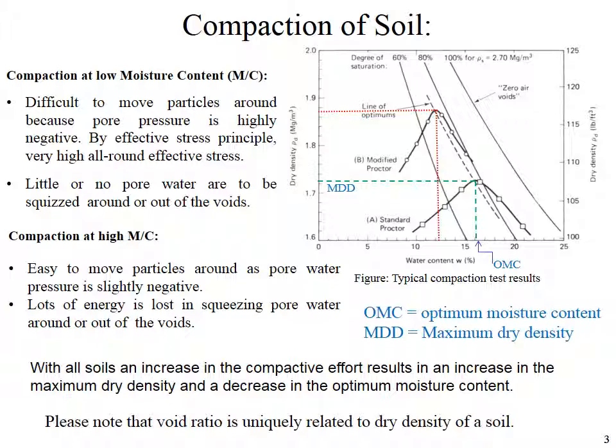Compaction at high moisture content. Easy to move particles around as pore water pressure is slightly negative. Lots of energy is lost in squeezing out pore water around or out of the voids.